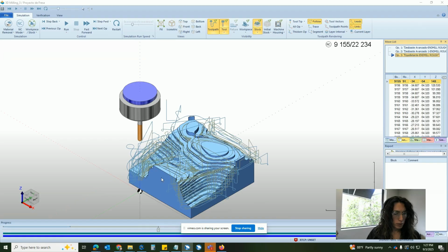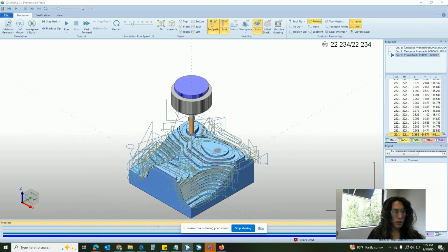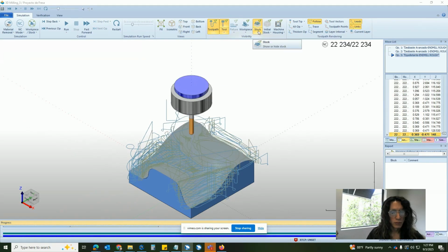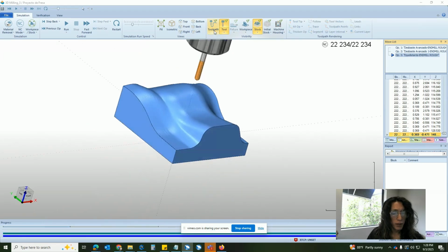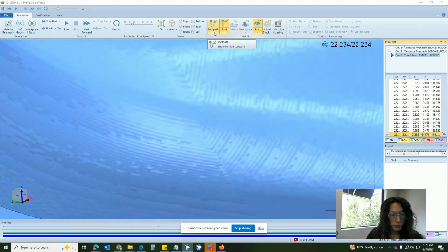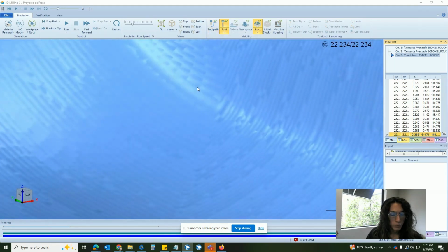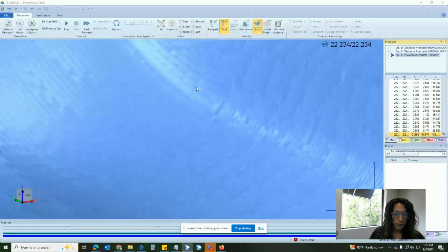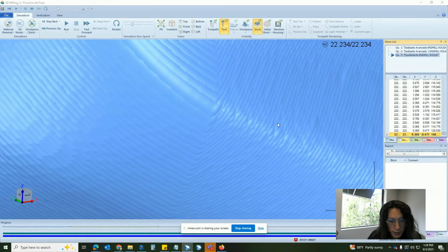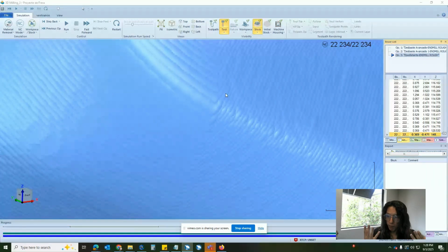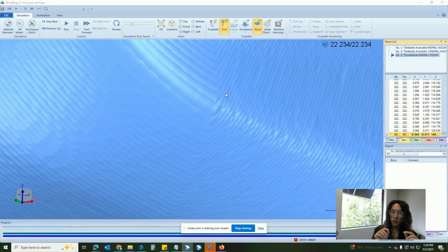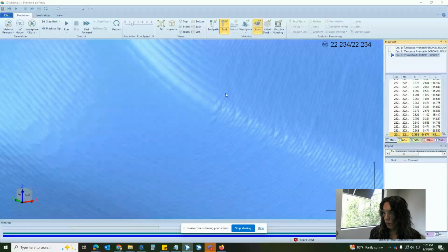Let's go into the equidistance and run the result. And let's remove the toolpath. So again, let's wait until it loads. This is what I'm talking about. Can you see it? Right here. So it's not a bad toolpath. The problem is those little markings you're going to see on your finish, like Robbie brought up. It's going to happen.